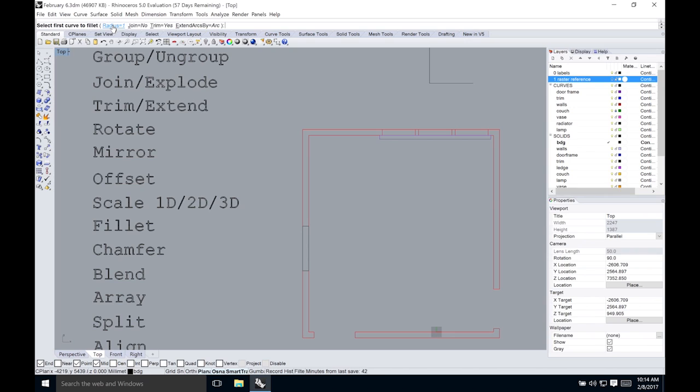So first of all, before you select any curves, you want to make sure that you have the radius you want to fillet with, and for me it often takes a number of trials and errors to figure out, unless I actually know what radius, but 1 is probably really small because that's 1 millimeter.